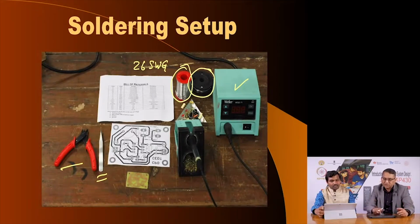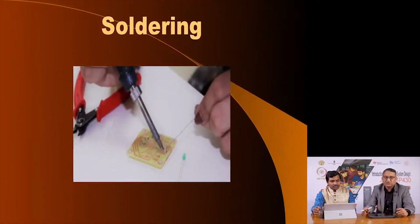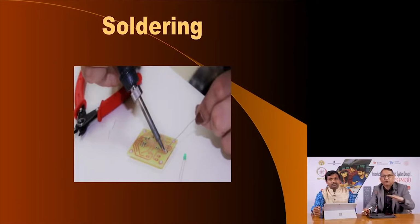The way to solder components is that you must solder components with the smallest or lowest profile first, which means you solder resistors and SMD components first, then you can solder IC bases or LEDs, and as the height of the components increases, you should solder them later. Once you have done that, you can snip off extra leads of the components with this cutter, as you see here.